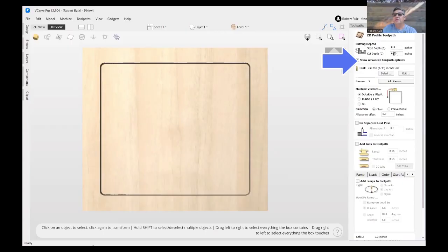And remember that I said our material size was 0.80. Okay, so we want this to cut all the way through. All right. If your material is a little bit thicker than that, let's just say 0.81, it'll leave a really thin paper-like layer left over, but it's easy to trim that off or sand it off. Okay. But you want to get this as accurate as you possibly can.